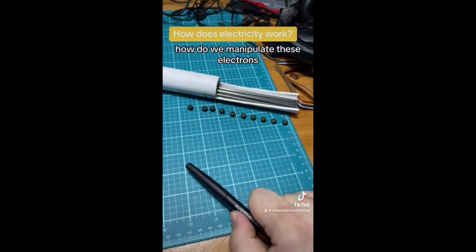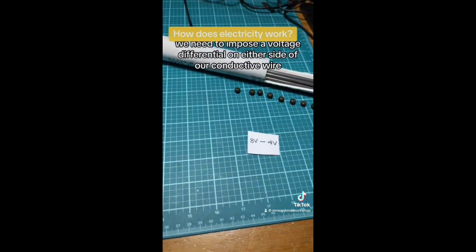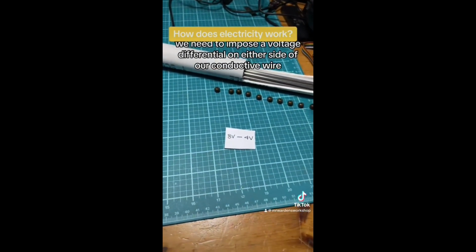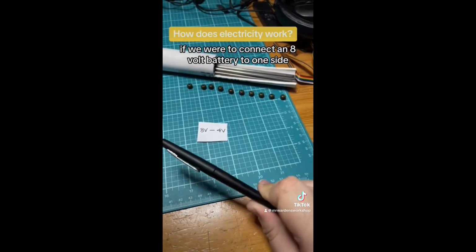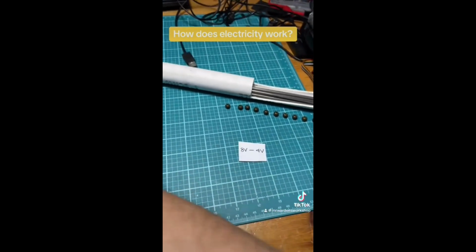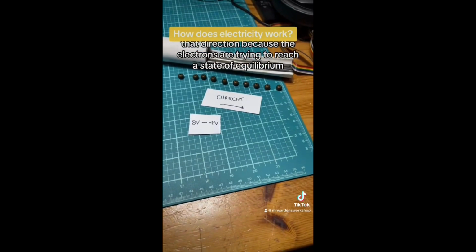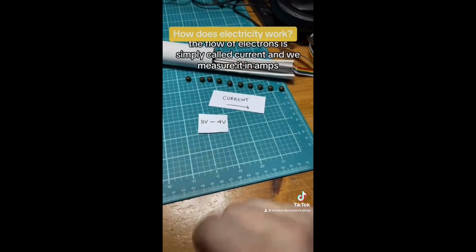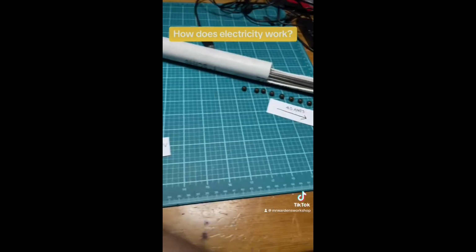But how do we manipulate these electrons? How do we get them to flow one way or the other way? We need to impose a voltage differential on either side of our conductive wire. If we were to connect an 8-volt battery to one side and a 4-volt battery to this side, the electrons would flow that direction because the electrons are trying to reach a state of equilibrium. The flow of electrons is simply called current, and we measure it in amps.